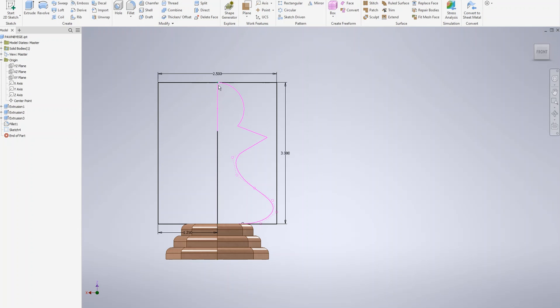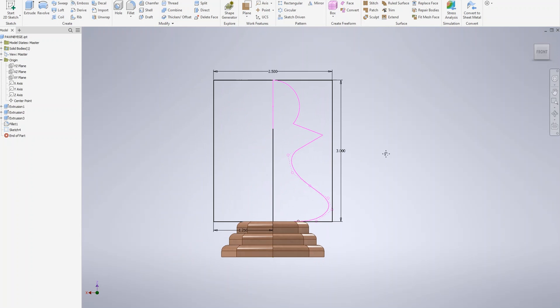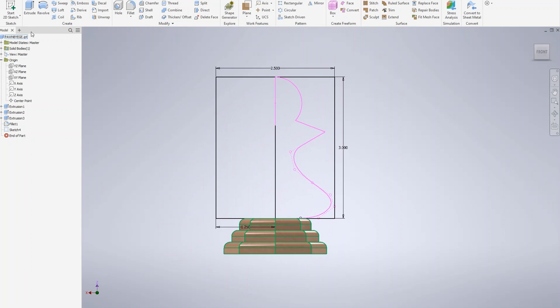The vertical line is made out of two pieces, so I did not draw one single vertical line. I just created two, one vertical line and another one in the center. And I trimmed off anything extra out of the circle. And we have this shape of the pawn. We have a spline, and the spline goes all the way to the center. All right, so here we're all done.